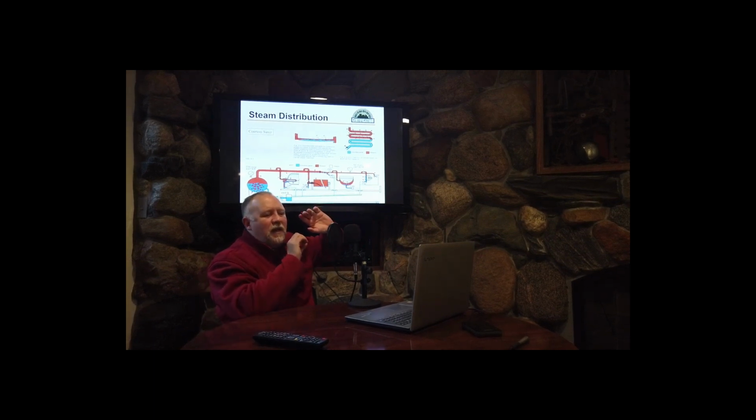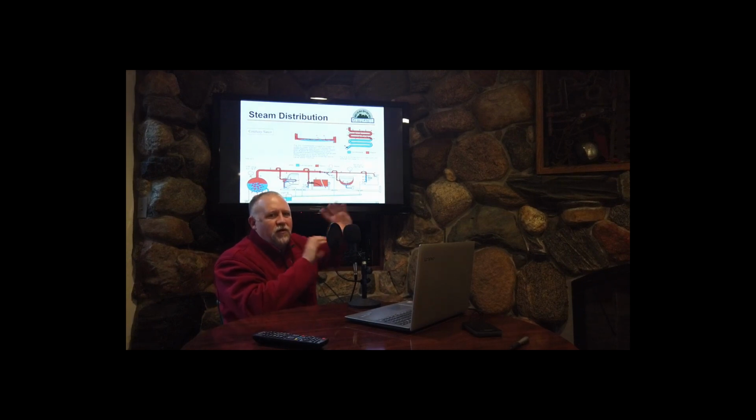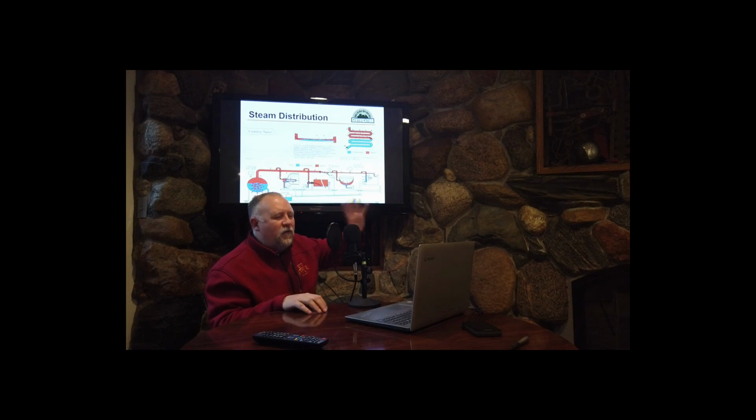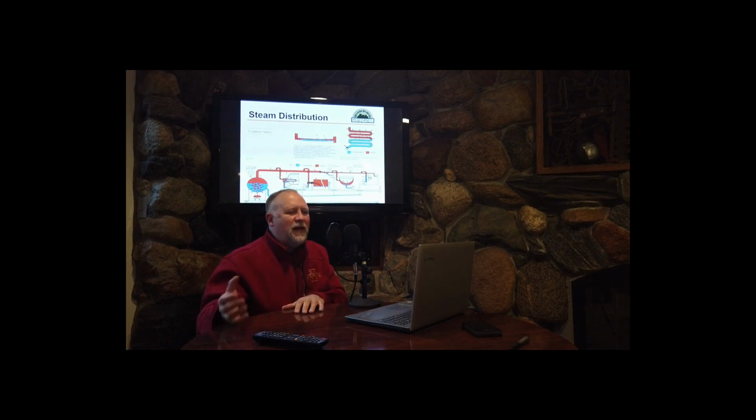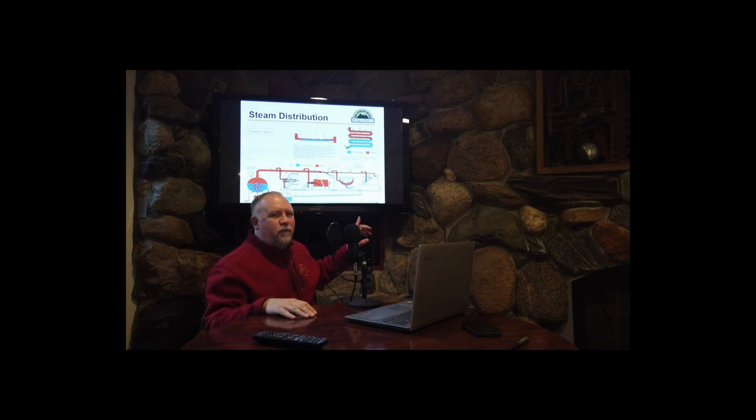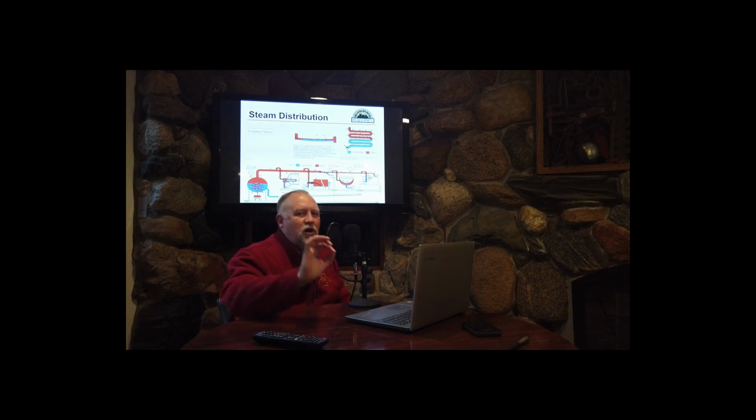They get it to start what I would call puffing or chugging away. And those spikes in pressure, it was 1 psi steam, and those pressure spikes got up to 12 psi, and then they had a safety blowout at the end of the pipe to relieve that pressure. So a 1 psi steam system can cause pressure spikes of 12 psi.